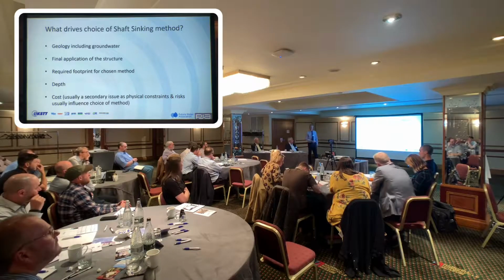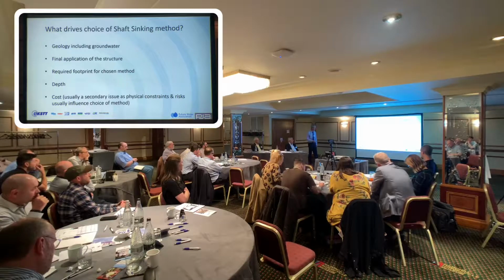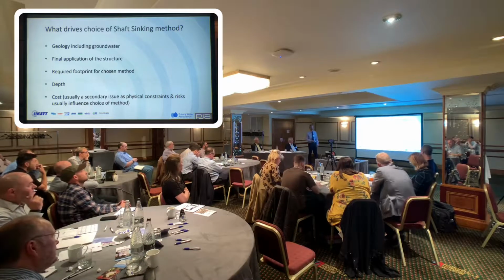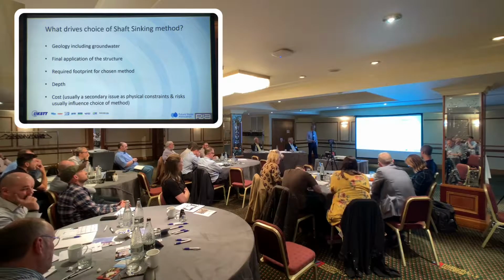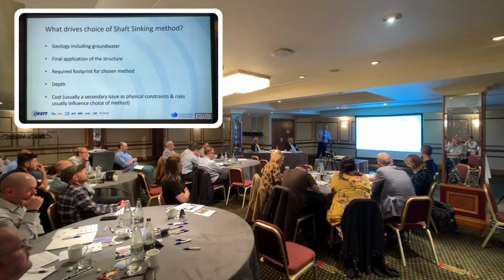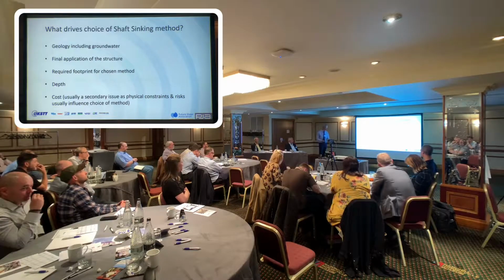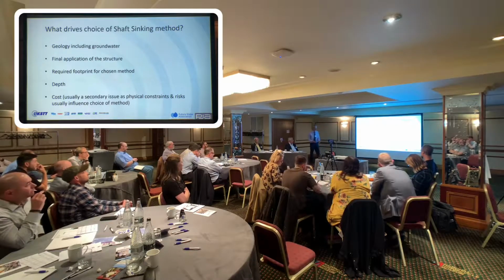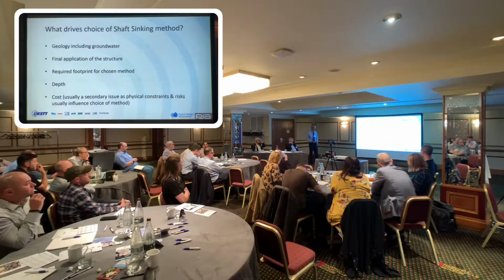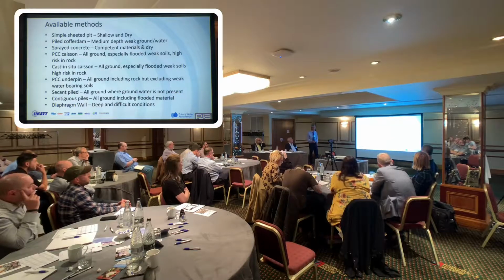Need two football pitches to set it up. Yeah. And cost should be a secondary issue. It's usually a secondary issue. The physical constraints and risks, and how you can deal with the ground conditions, is by far away the most important thing in terms of shaft sinking method.